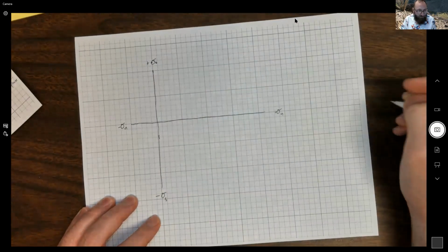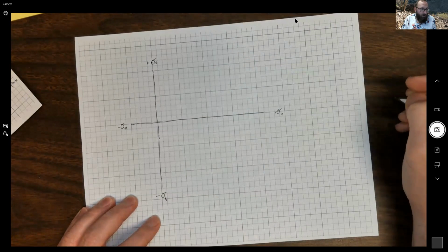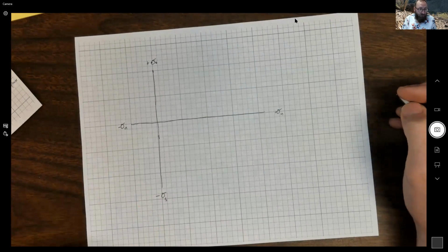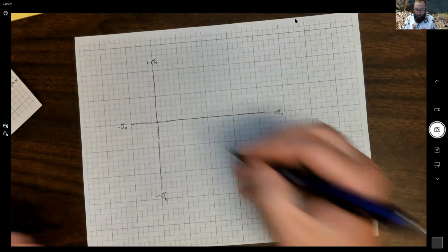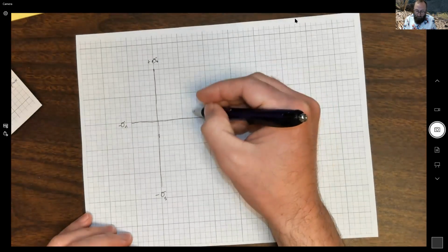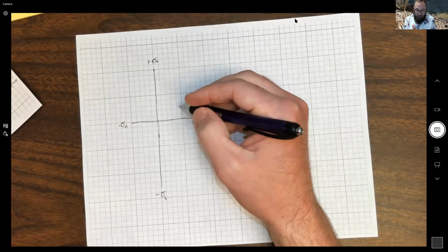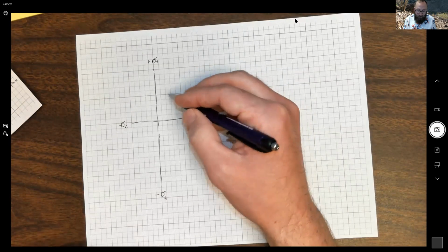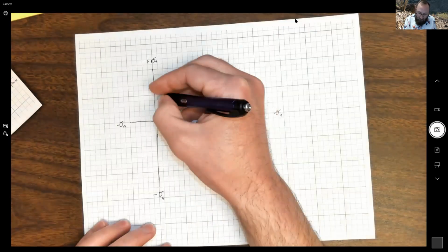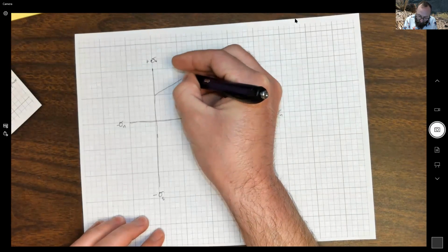From deformation experiments, we're able to plot and define the failure envelope for a particular lithology by marking the failure points for each experiment on a Mohr circle. Recall, we would draw a Mohr circle and look for the angle between sigma 1 and the failure plane that the faulting occurred on, and plot those points on here. Again, we would end up defining our failure envelope.